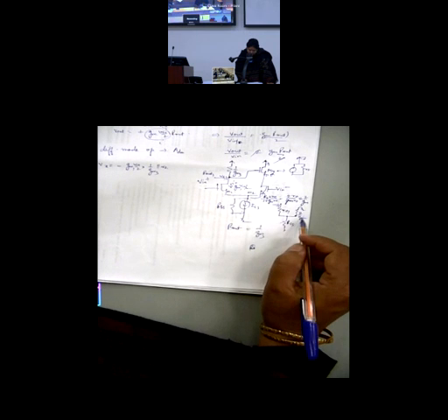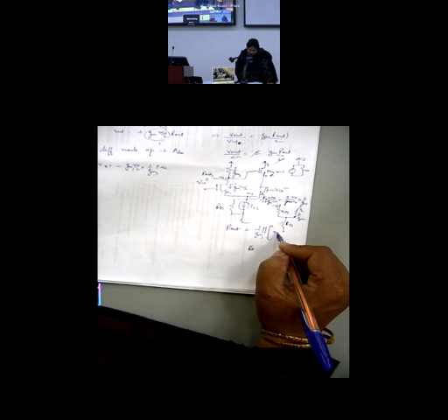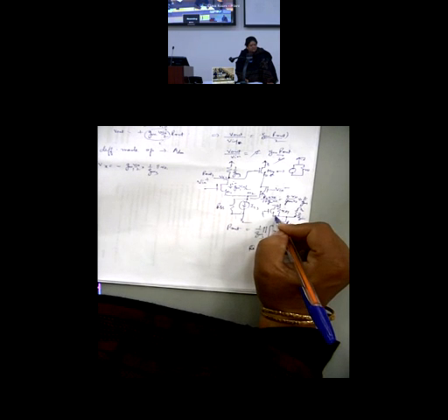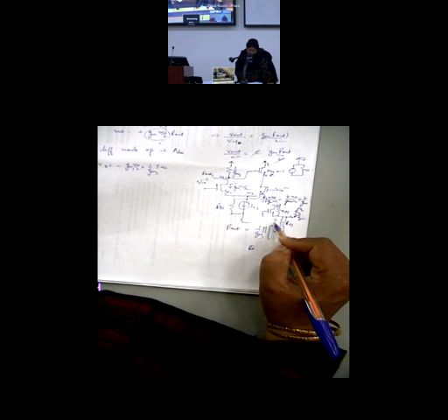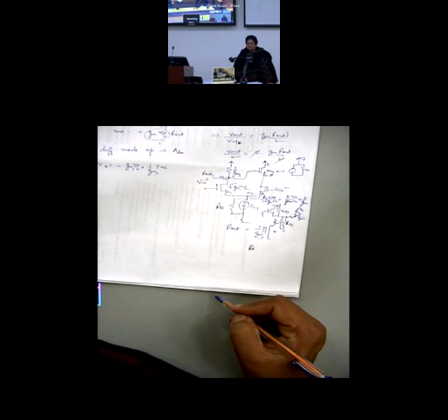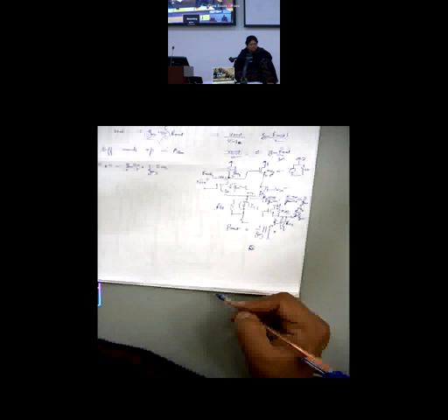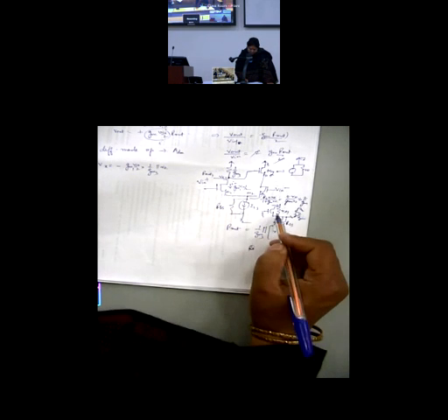So what is my R out now? Compute. It would be 1 by GM3 parallel this whole component. So can I say it would be RO1? Rather, remember you have a MOS here. So cascading will come. I can remove this from here and put it in parallel to this. It's like a cascade, a MOS with source degeneration. I can apply the concept of source degeneration to this MOSFET.